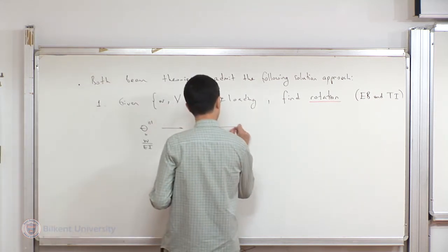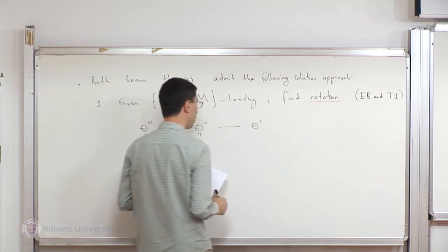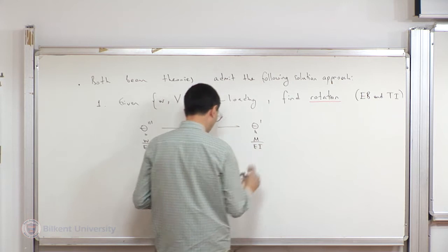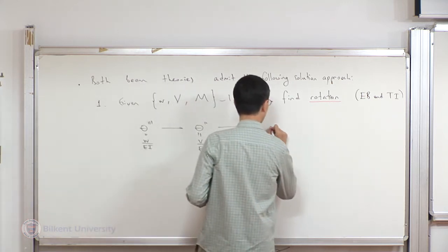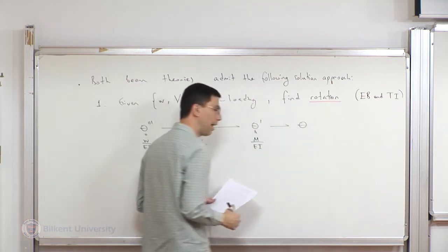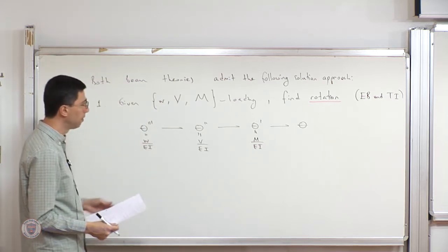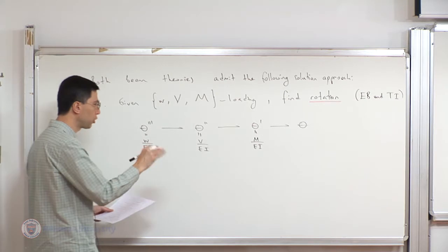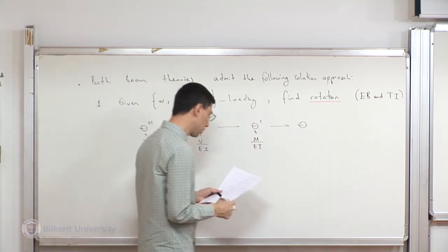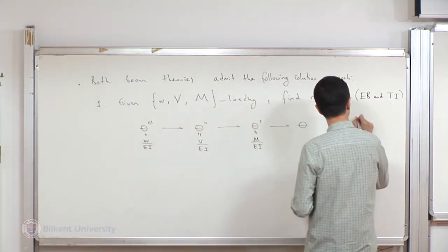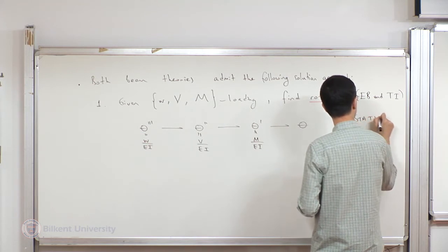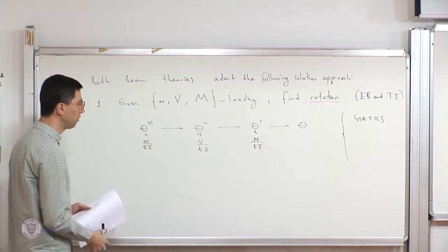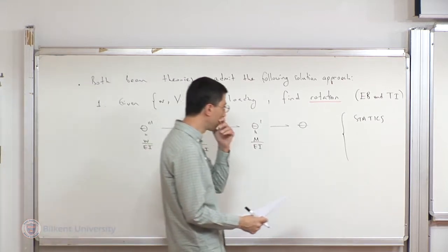And then I can integrate towards the first derivative, which I know will be M over EI, which you can finally integrate towards the rotation as a function of the lateral position x1. So this is the rotation of the cross-section. These results, remember, are based on statics. So the lower set of equations are from statics. They've got nothing to do with any sort of deformation.